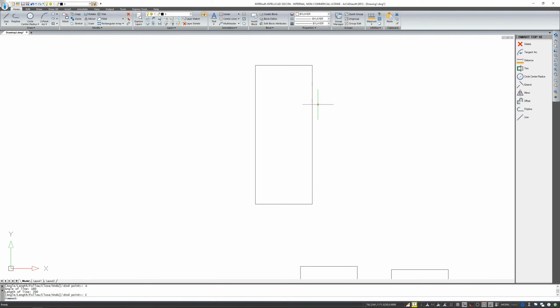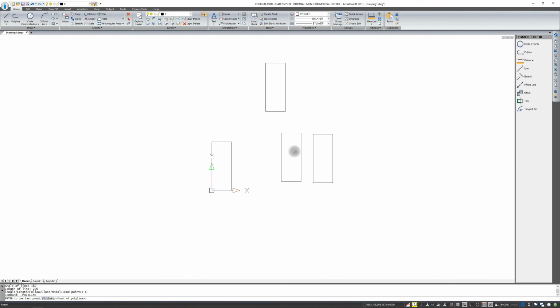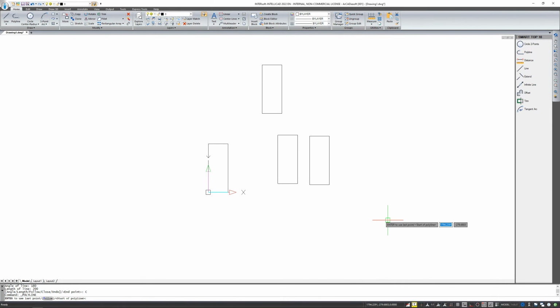Whether it will be a rectangle with a different angle or whether it will be parallel and perpendicular to the screen, it will all depend on your design. There is of course an easier way to draw an element. You can just turn on the Ortho mode and start drawing. This is the button to turn on Ortho here on the status bar at the bottom, or the F8 key if you prefer.